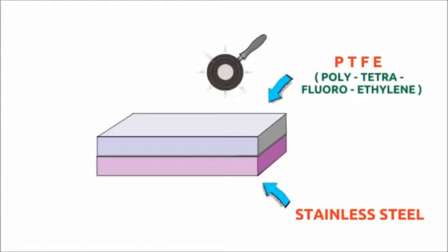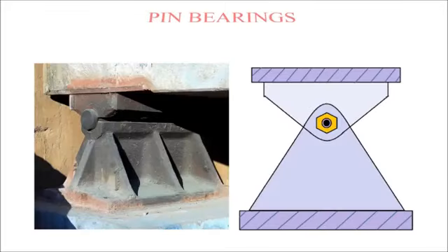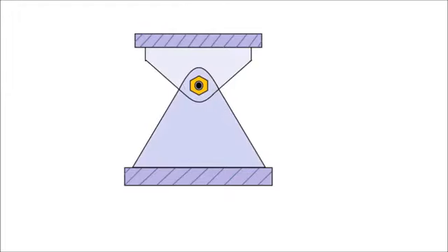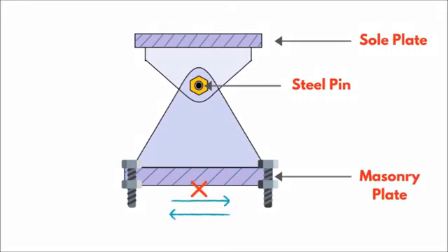PTFE means polytetrafluoroethylene, widely known as Teflon, which is also used as a non-stick coating for frying pans and other cookware. It has one of the lowest coefficients of friction of any solid. Pin bearings are one of the oldest types of bearings, permitting rotational movement and preventing translational movement. The pin transfers the forces by rotation from the sole plate, which is attached to the superstructure, to the masonry plate, which is attached to the substructure. These plates are usually anchored by bolting to the substructure, which resists the translational movement.